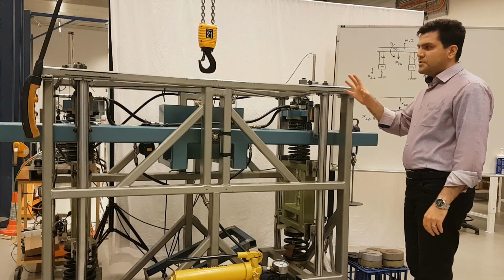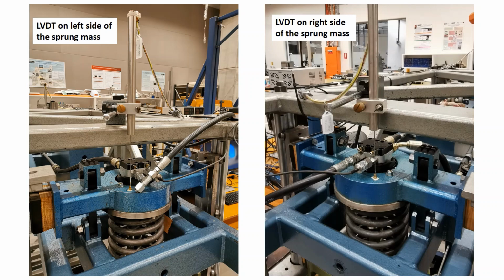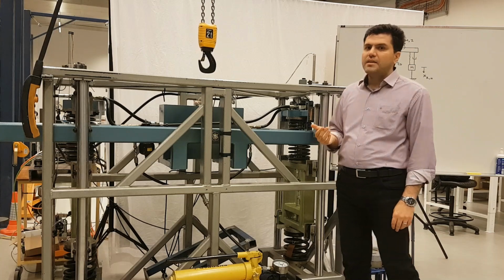So the sensors here are LVDT. In this experiment, we are using LVDT, or basically linear variable differential transducer, to measure displacement of the structure at different points. LVDT is a common type of electromechanical transducer that can convert the rectilinear motion of an object to which it's coupled mechanically into a corresponding electrical signal. LVDT sensors are readily available that can measure movements as small as a few millimeters up to several centimeters. We use LVDTs to measure displacement at 4 points.